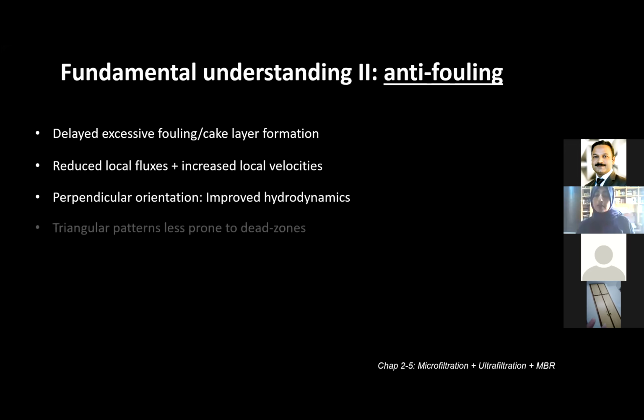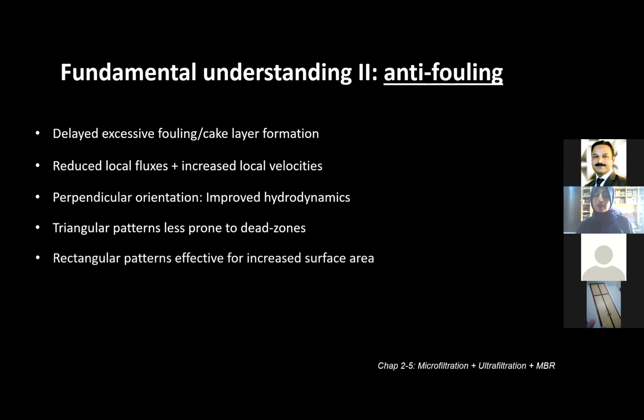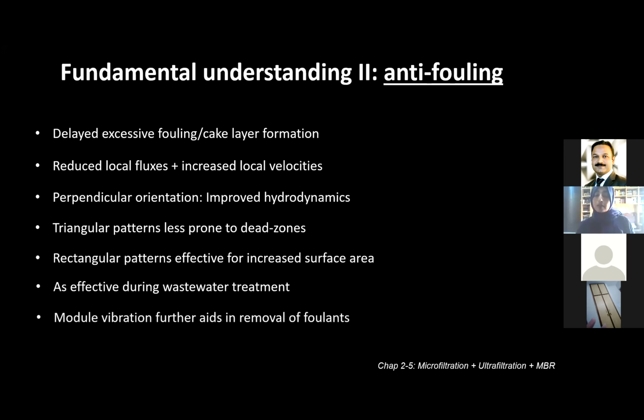In terms of surface features or surface pattern dimensions or shapes, triangular patterns were less prone to dead zones and were providing better hydrodynamics, but rectangular patterns were more effective for increasing the surface area of the membrane. So depending on your application, you can choose the pattern shape. And also, these membranes were similarly effective in wastewater treatment, and hybridizing and combining it with vibration brought us more control over the flow over these membranes.